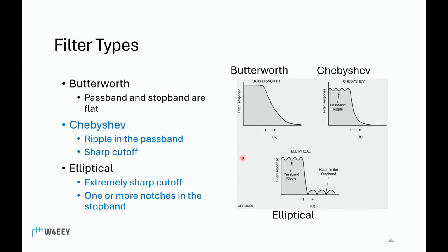And you might be thinking, well, okay, this is nice. What if I needed a sharper response? Well, you can actually put a couple of these in series. You could have two Butterworths. That'd be a two-pole filter. You'd still have the smooth response, but the skirt would become steeper. And that's going to become important when we look at digital filters, because it's very easy to adjust the skirt shape in a digital filter.